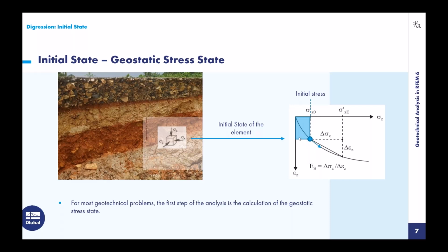What we don't need is this displacement that is calculated as well. We are not interested in the deformation that happened to the soil due to its self-weight. If we look at this picture, this is the start situation, and we want to know the deformation that happens for the further loading.